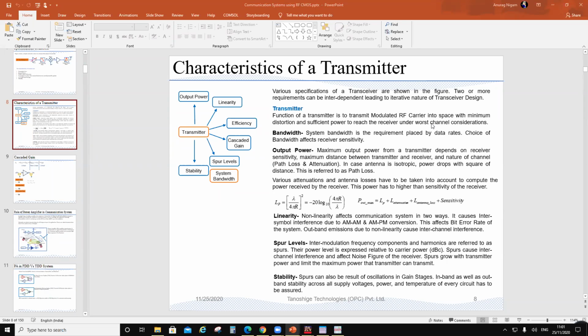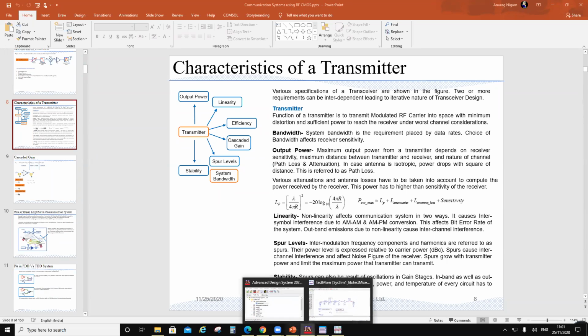It means that your 1 dB compression point was around 3 dBm. So TOI is related to the absolute power you are going to do, and gain is something which your transceiver, basically your DSP output, decides.